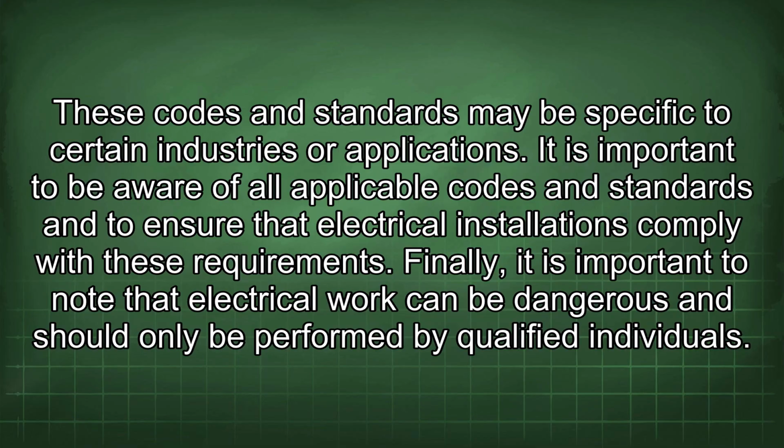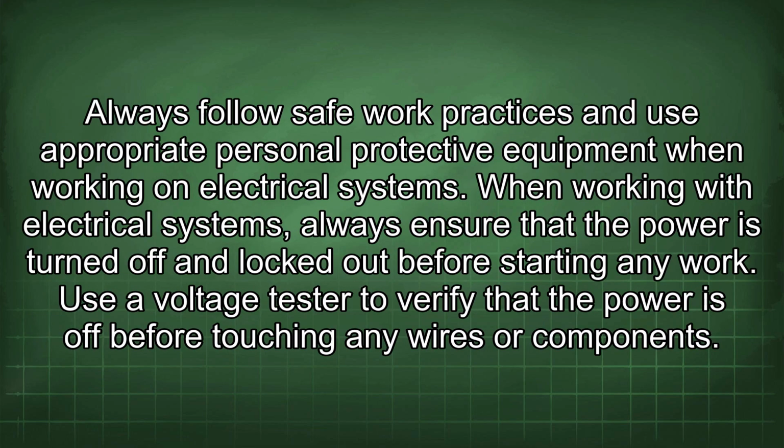Finally, it is important to note that electrical work can be dangerous and should only be performed by qualified individuals. Always follow safe work practices and use appropriate personal protective equipment when working on electrical systems. When working with electrical systems, always ensure that the power is turned off and locked out before starting any work. Use a voltage tester to verify that the power is off before touching any wires or components.